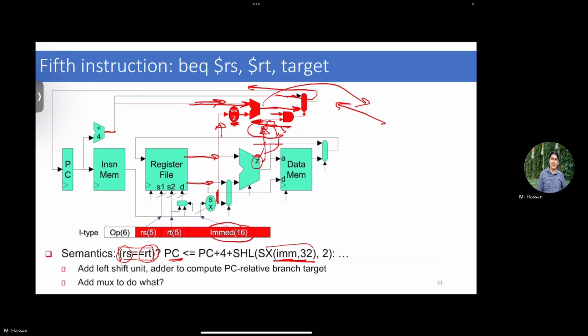It's very simple. Now, if I have a branch, then this mux will enable the second path, right? And assume that the branch is taken. Taken means the condition is true, which means there is also an enable here. In that case, this path will be ignored, and I will take the branch path here, and then the branch path will be loaded here. This was a branch, which means it's not a jump, so I continue with that path and I update the program counter. What if it was a branch, but the condition is false? In that case, this enable will still be false, which means you take the normal path again. So you go back to case 1.